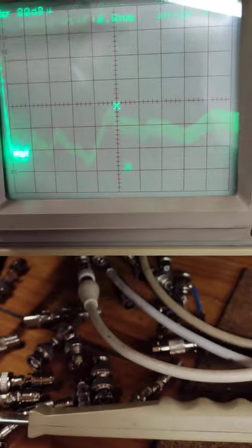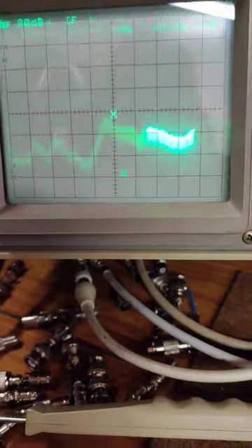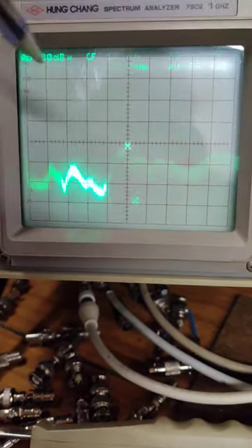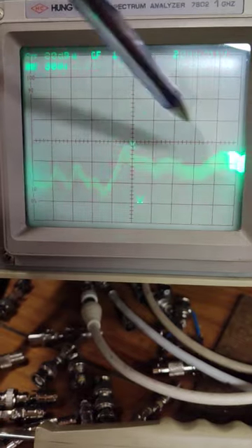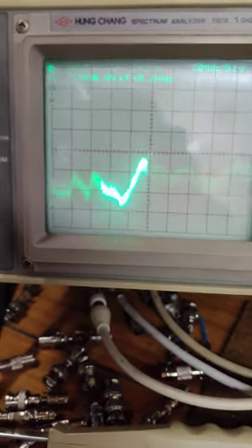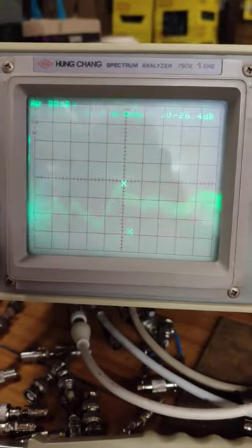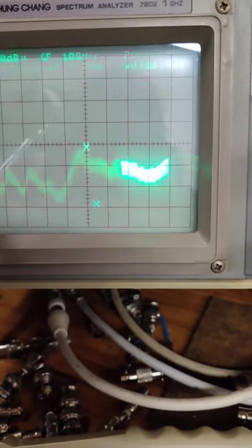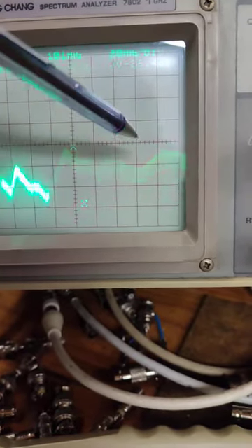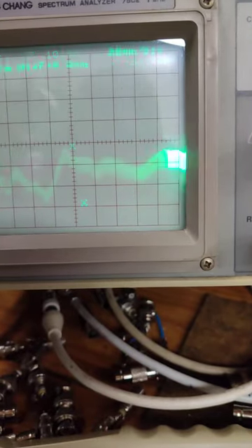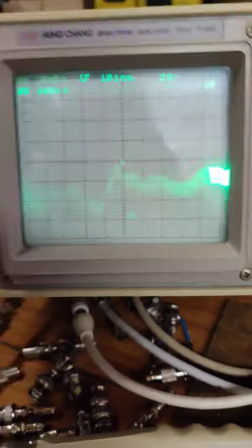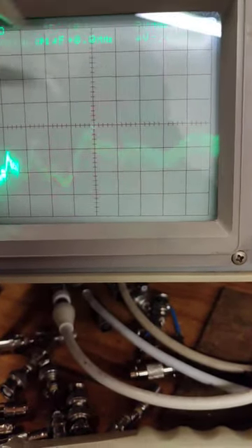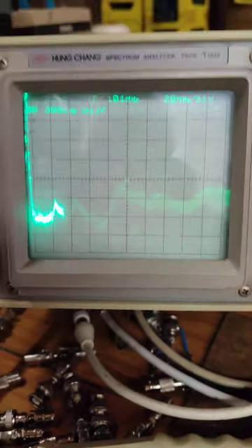Okay, so it's 5 times 20, that's 100, and 100, I'm measuring from 0 to 200, I'm confusing myself. All right, so we got a very broad spectrum. If you remember right at the beginning of the video, I said you get the harmonics from 0 DC to many times harmonics of the actual interfering signals that generate noise. So I got a very broad spectrum, and I can actually see by how much I reduce.